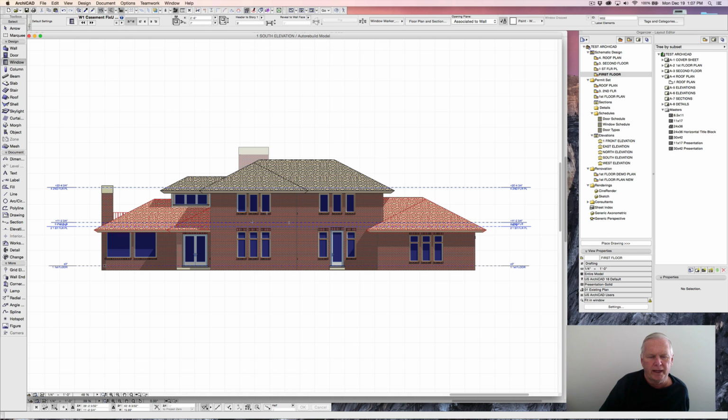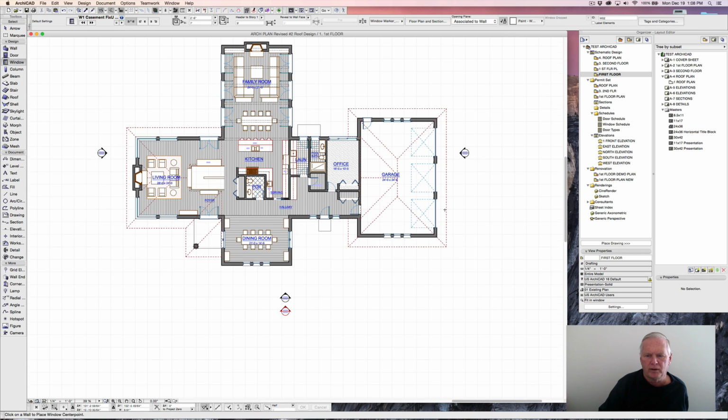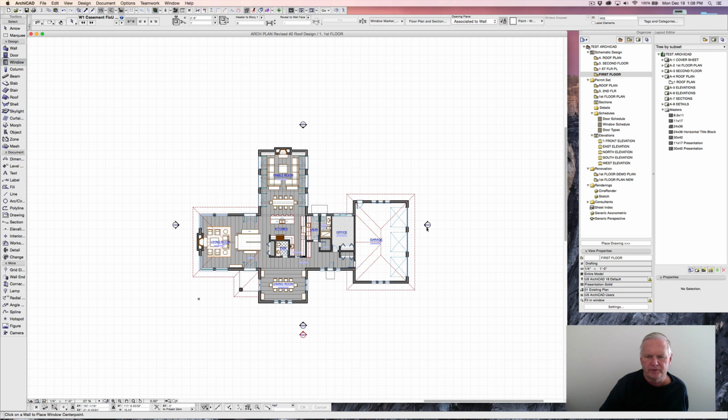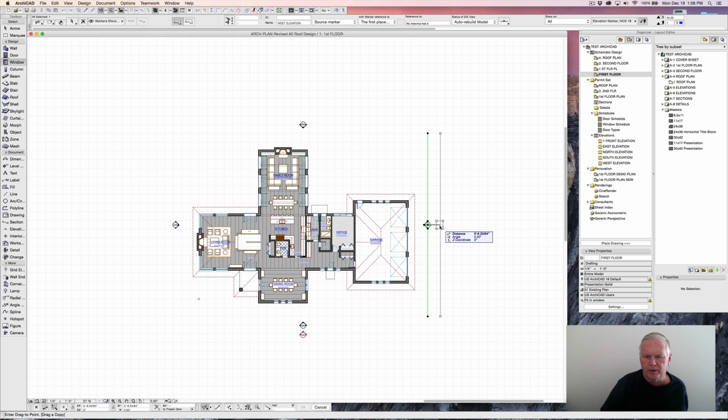elevation. And what we're going to do is jump back again to that first floor. And if you note, this is how I did the first one. I'm going to grab this elevation. I'm going to say move, copy, drag a copy. Just put it right behind it. Okay. And that one got thrown on here as 2 West.